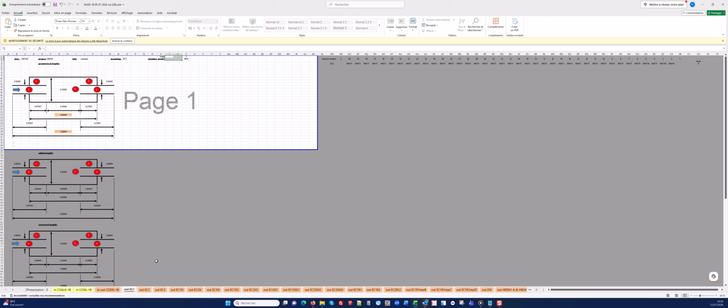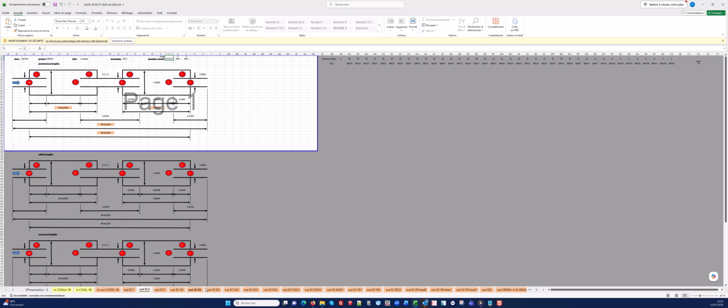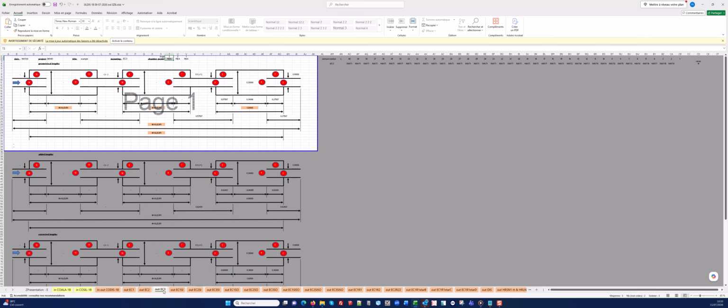Now we can switch to worksheet EC1, displaying all the dimensions of the expansion chamber as entered to check that what was entered is relevant. The upper sketch is displaying geometrical length, whereas we have also a sketch for added length and corrected length. This could be the same in case of other mountings if selected.